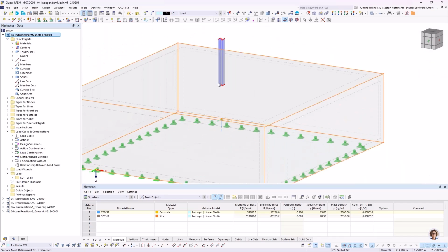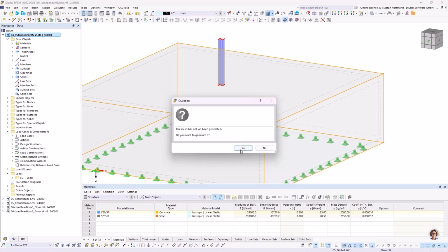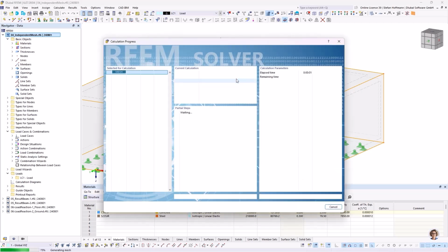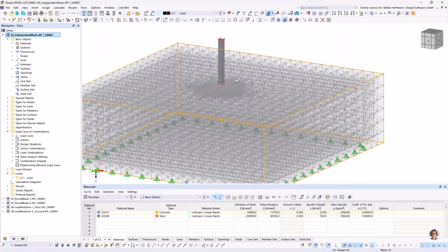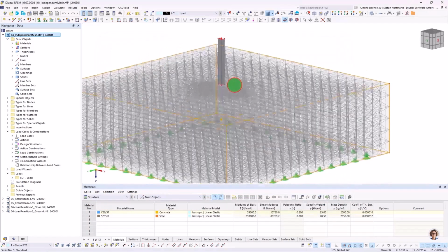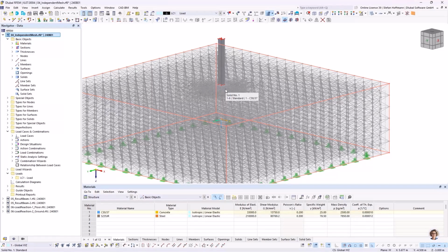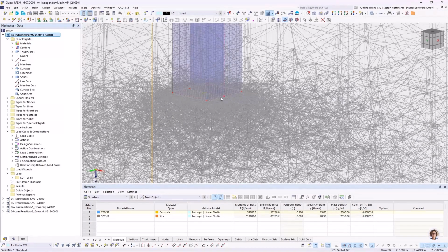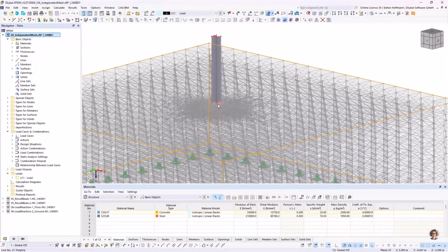And if you then have a fine mesh connecting to the solid body, it needs to be connected at FE mesh nodes. If we generate the mesh without any extra setting, the mesh will most likely have such a fine representation, because the fine mesh of the surfaces needs to be directly connected to the solid in the ground.